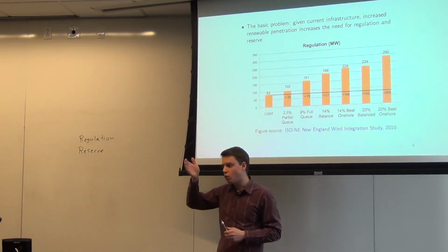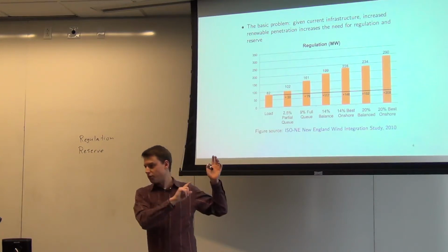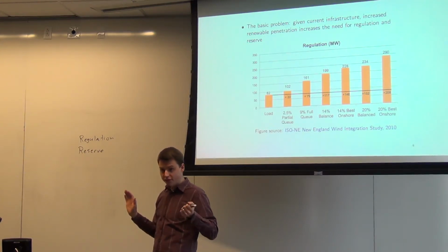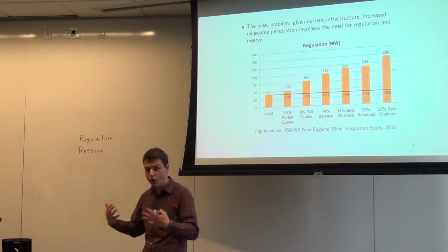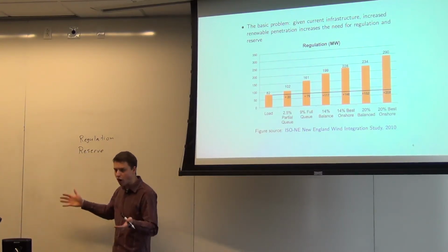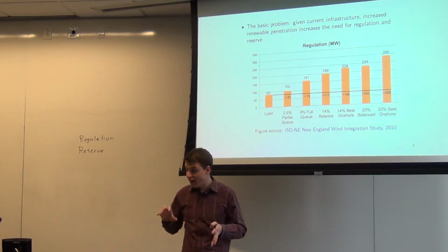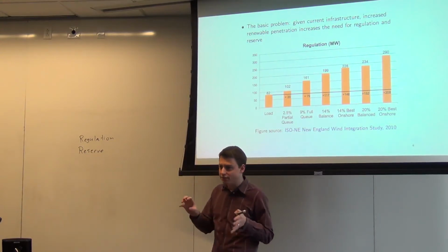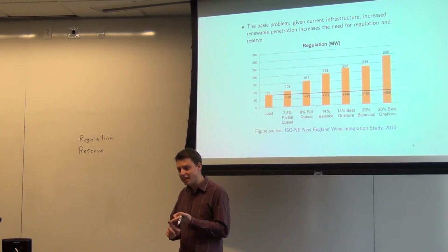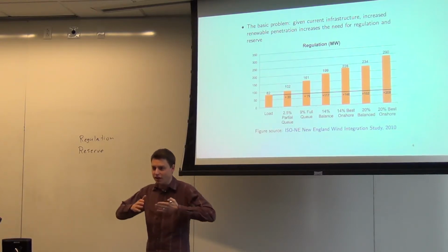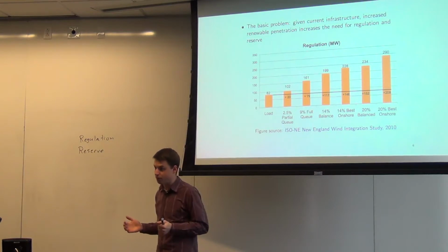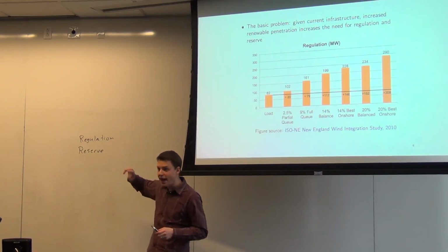When you have sudden spikes or drops in power generation, as we saw from the dynamical systems, you will have a corresponding slowing down or speeding up of the frequency in the grid. And this can be a big problem because those big generators take some time to get going again, right? If you want to spin these things up, it takes a little bit of time. And so regulation services, as a broad umbrella term, refers to extra power that the grid has available whose main purpose, speaking a little informally here, is to maintain the stability of the grid, to maintain frequency and to ensure that there isn't a huge voltage spike or drop or a frequency spike or drop due to a big drop or increase in demand.